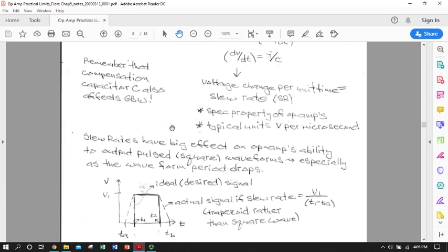The trick comes in applying it and understanding what time rate of change of voltage we're asking our op-amp to follow, and then making sure it's the output. Because obviously if we have a certain amount of voltage gain as a result of our op-amp, and we have a constant frequency, we're not changing the frequency as we go through the op-amp, the delta V over delta T is going to get much bigger when the delta T stays the same, but the delta V increases because we've got a certain amount of gain.